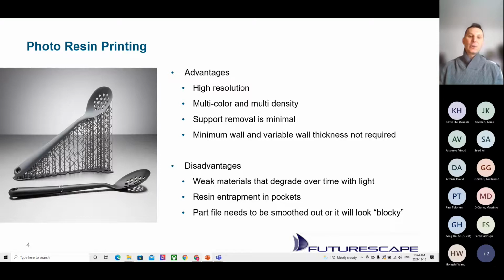Another thing is that when you're printing, you actually have an epoxy that's liquid. You can have entrapment of that epoxy inside pockets and voids and whatnot. So planning your part to make sure that no resin gets stuck in the part is difficult.